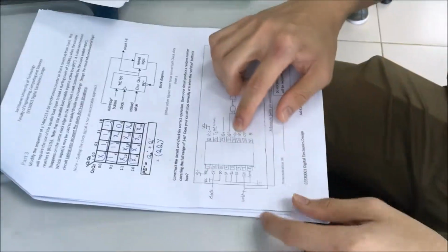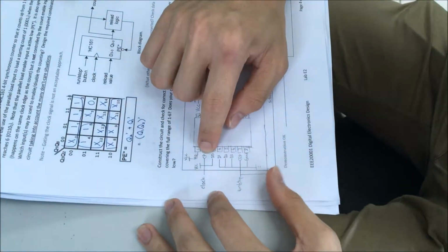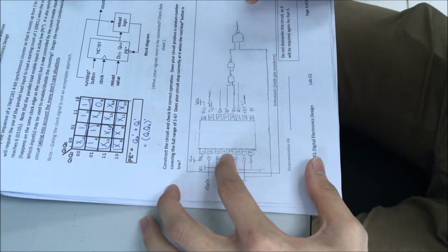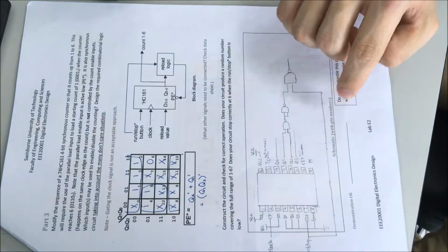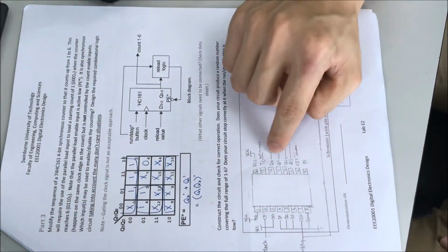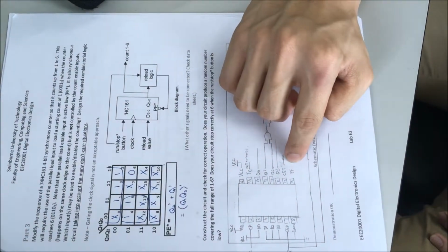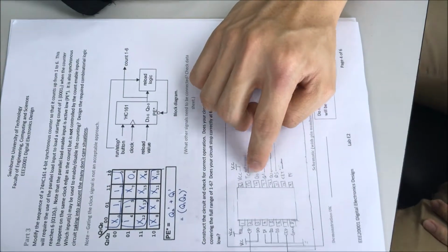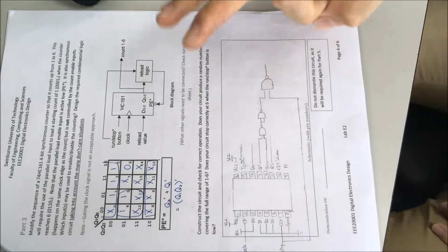So here, this is the design of the circuit. We connect MR to VCC, CP connected to clock, and D0 is connected to VCC, D1, D2, D3 are connected to the ground. CEP is interconnected with CET and is connected to the switch module, and ground is connected to ground. Q0, Q1, Q2, Q3 are our inputs, and the PE is the result of the output, and TC is not connected. VCC is connected to VCC, and in this circuit we have 3 NAND gates.